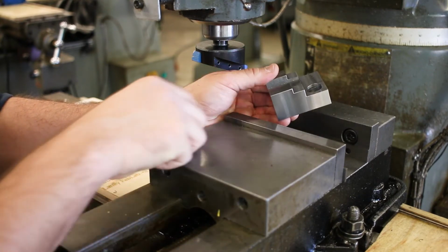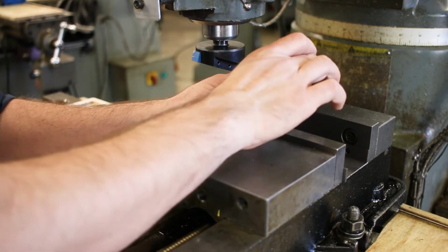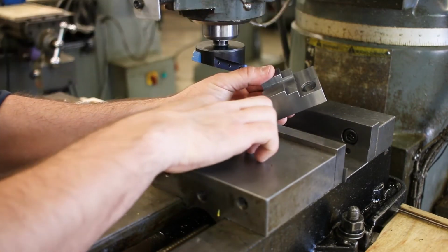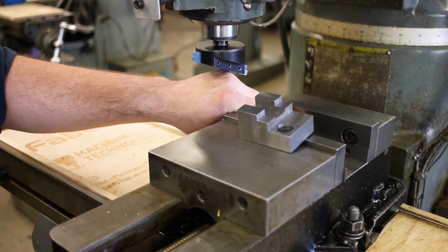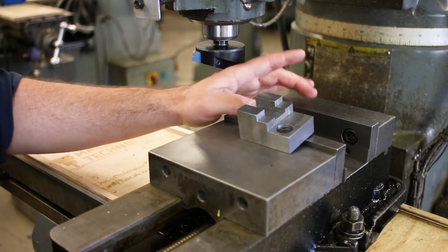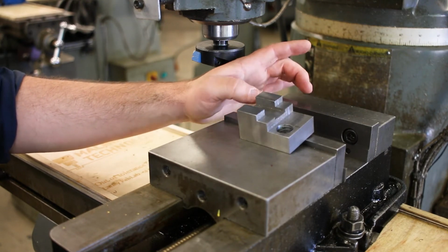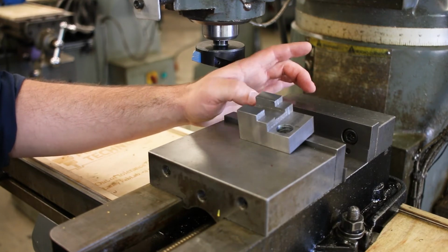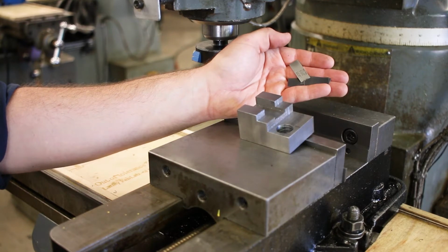So side opposite C and side opposite D. Those two surfaces need to be parallel to C and D. And so the way that we're going to do that is by hammering the part down onto the parallels. And in order to make sure that the part is truly down on the parallels and we're going to get a parallel surface, we're going to use the shim trick and put shims between the corners of the part and